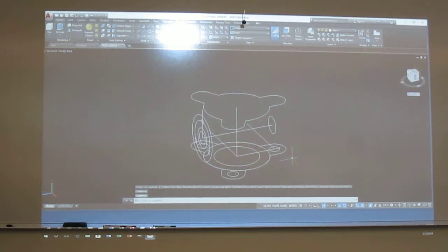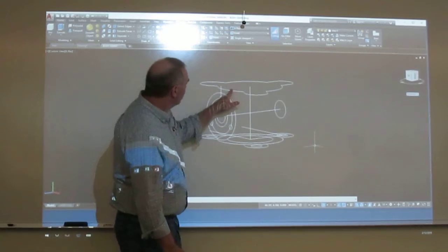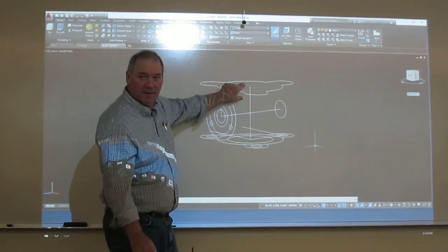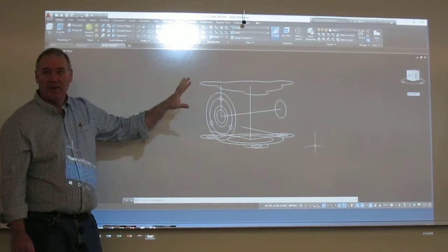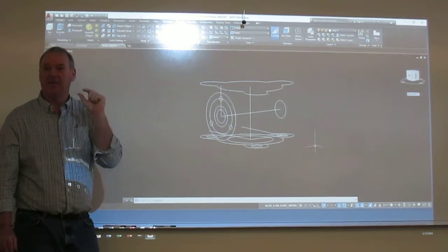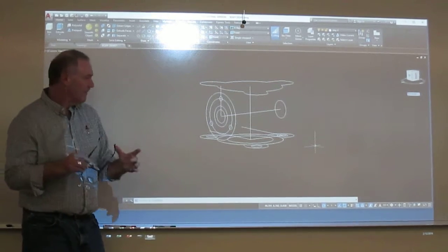Now, the order that you do things is almost as important as how you set stuff up. And a lot of people get caught up thinking, oh, I got to create this shape in here where these two meet. Keep in mind, that's what your Boolean operator is going to do for you. You just need shapes of positives and negatives. That's it. Then everything else will fall together.